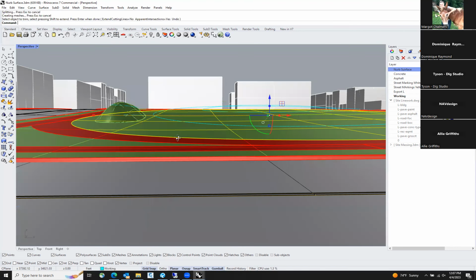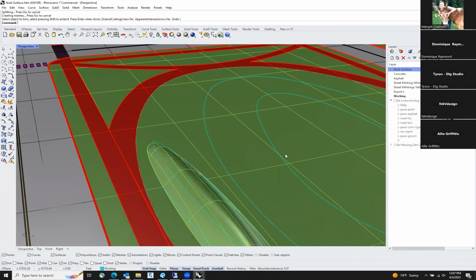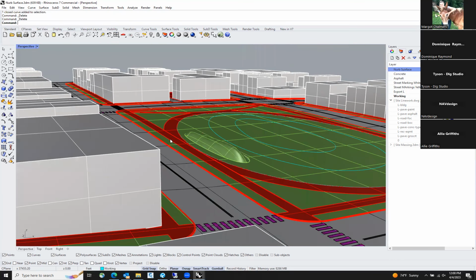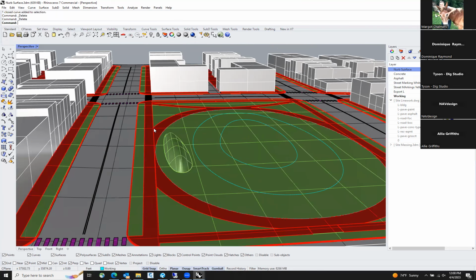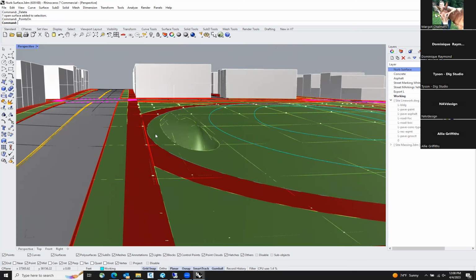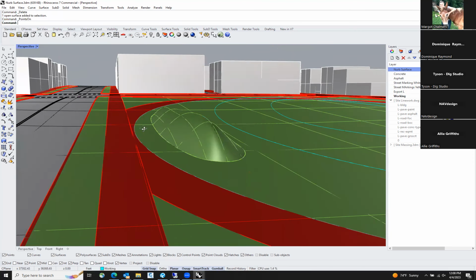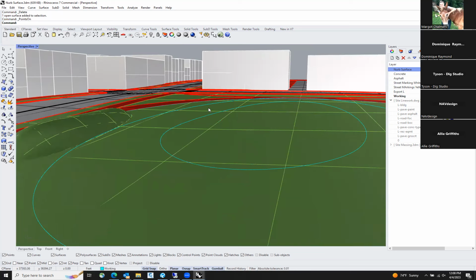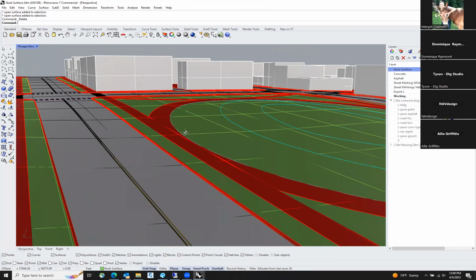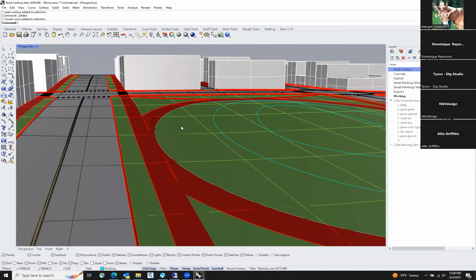So now you're left with your berm. So if you're working on a surface and you said, let's explore what berms look like, I wouldn't manipulate this surface because, again, you'll get creases in your model. I would just make a berm separately and have it as a separate piece. So I'm going to do that here with this hill.